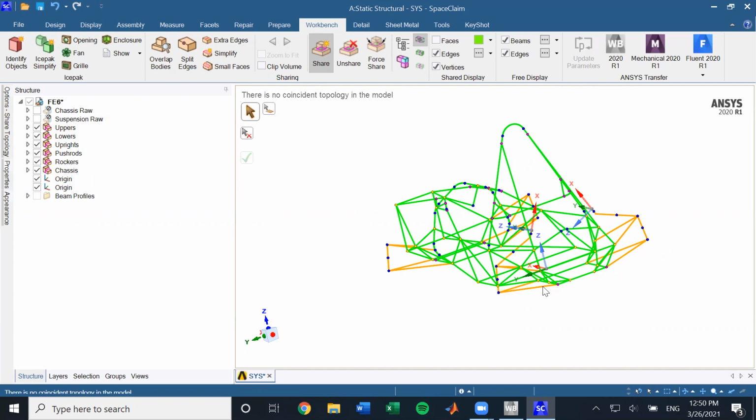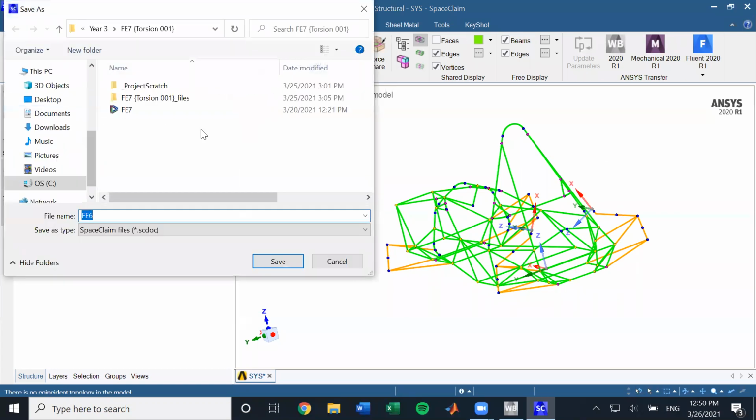And you'll see why that's needed for the joint definitions that we are going to do. If we share the entire thing at once, it'll only import it as a single folder of parts. Whereas since we did it separately, we're able to interact with each component also separately. I'll make sure to stress that again or show you in practice where that is important.